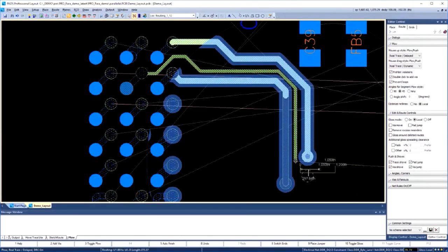Simply click once to start. If a path is blocked, the route will enter a shadow mode until the trace reaches open space and a valid push and shove routine is able to be completed. For large bundles of nets, this minimizes the amount of traces attempted to be pushed and shoved when interactively routing, and ends up increasing trace quality while reducing mouse clicks. I've also noticed in extreme cases of net density, this algorithm helps to improve performance by holding off on the push and shove routines.